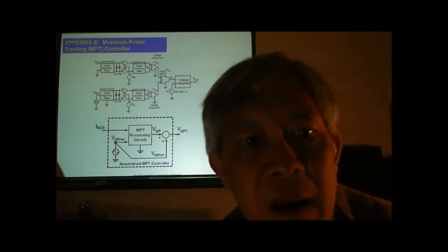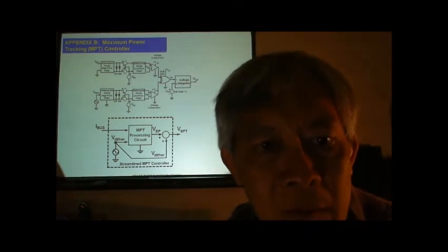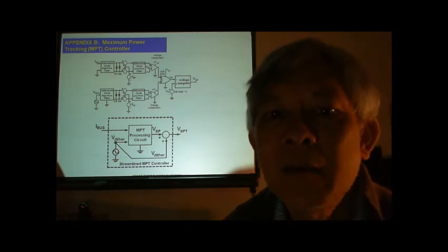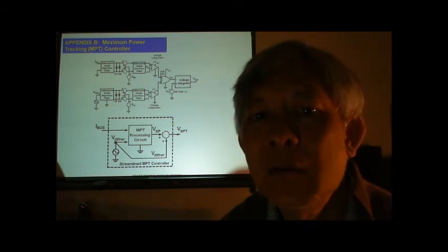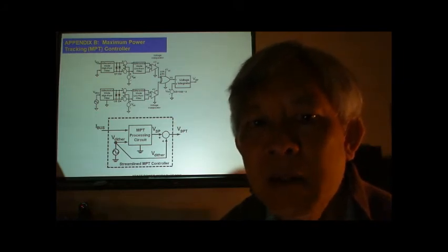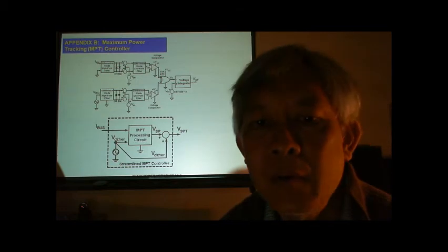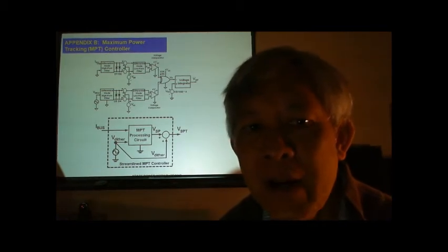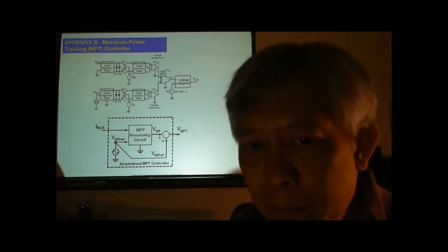The digital signal is also added back to the voltage set point VSP, so that the voltage set point VSP also contains this low frequency digital signal, and the total set point voltage VSPT becomes the command signal for the input voltage regulator, so that the system sourcing voltage can be controlled to track this set point voltage VSPT.